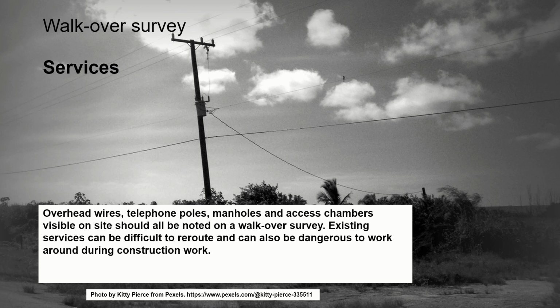And they can be difficult to move, they can be difficult to reroute. Moving electrical cables requires the consent of the supplier and can be quite costly and sometimes needs an upgrade. So understanding where these things are has a cost implication for your client, but there's also a safety implication. Working in and around overhead services can be dangerous, especially if there's lifting equipment or high vehicles, or we're expecting scaffolding to be erected. So we have to think about where the services are when we're asking people to work around them.